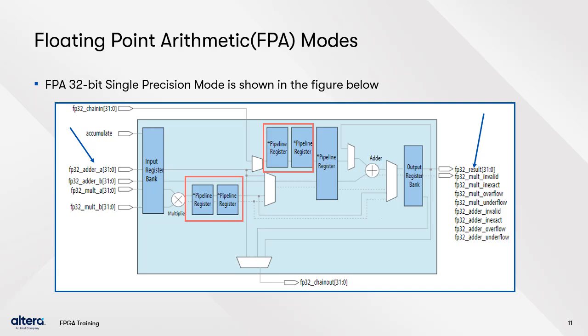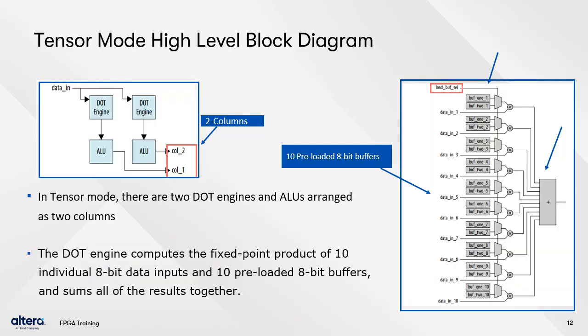Adder or subtractor mode allows you to perform addition or subtraction of the given inputs. The floating point adder or subtractor mode supports the following exception flags: invalid, inexact, overflow, and underflow. The tensor mode high-level block diagram is shown in the figure.